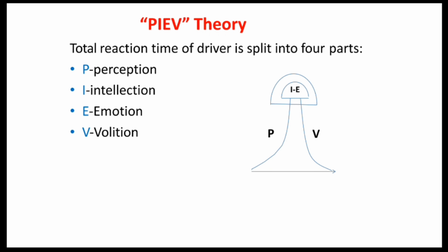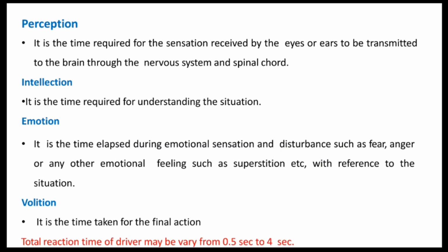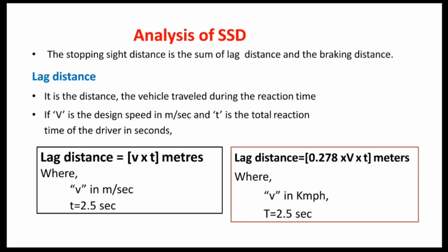So this PIEV theory works on the PIEV time of the driver, which depends on several factors such as the physical and psychological characteristics of the driver. The total reaction time may vary from 0.5 seconds for simple situations to 3 to 4 seconds for complex problems.